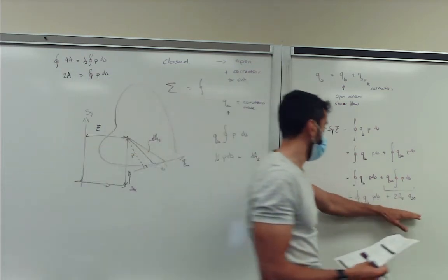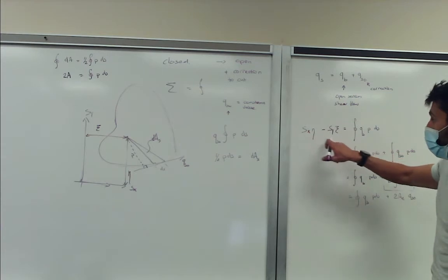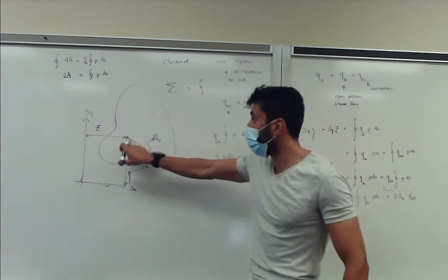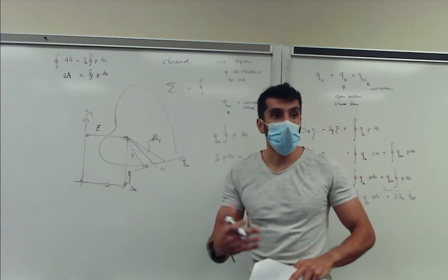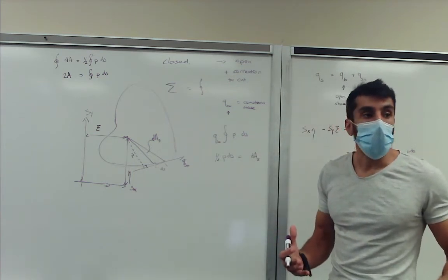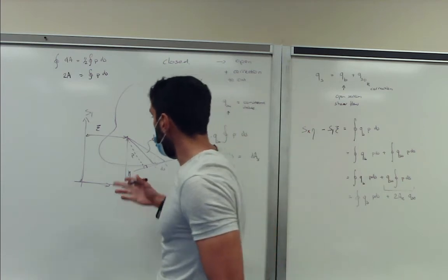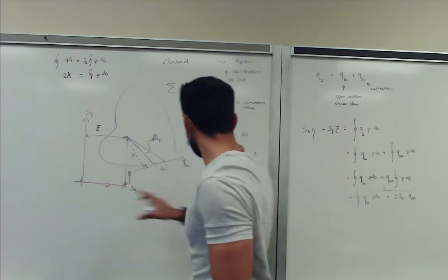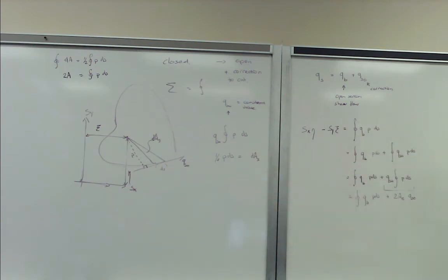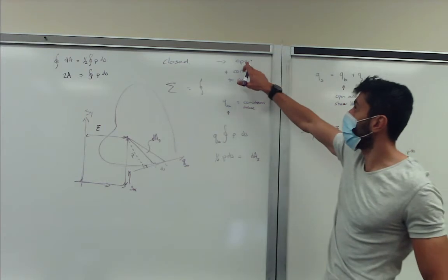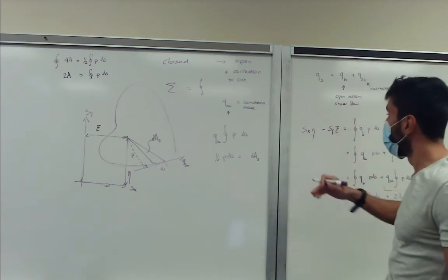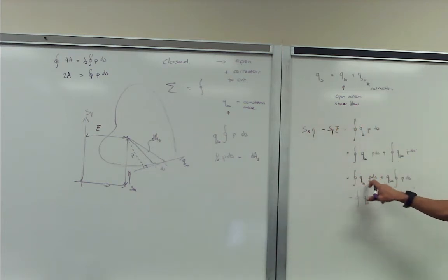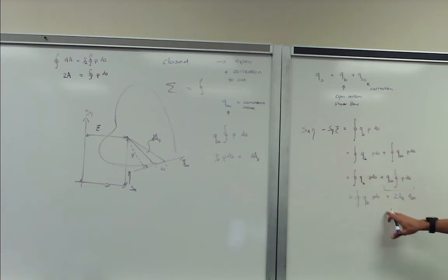Because now on this side of the equation, the shear forces are given. The location where you take your moment around is basically up to you. Always choose the most convenient location, where most of the shear flows go through or you intersect with most of your shear forces. In this case, a good position is located here, because then the left-hand side of the equation becomes 0, right? qb, that's the open section shear flows, so you already calculated that using the open section shear flow equations. So now this is known. The integral of qb, just evaluating the integral, is also known. And then the only unknown left over is qs0.